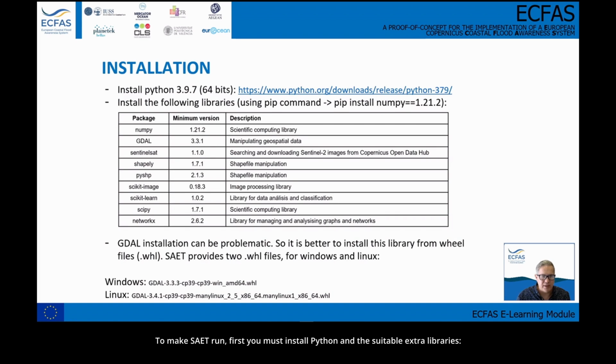To make SAET run, first you must install Python and the suitable extra libraries. You must install Python in the version 3.9.7 for 64 bits. In this link, you can download Python. The libraries that are needed to run SAET are those that are described in this table.